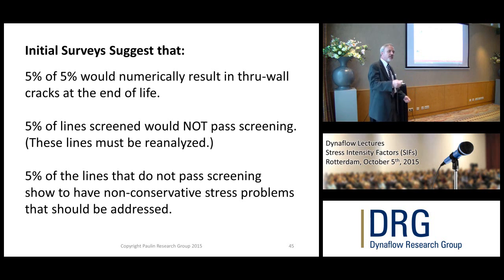And then you have to decide whether you want to start inspecting, and when to start inspecting. Because if you recognize this problem after 10 years and you're not going to have a crack that you can, probability-wise, find until after 20 years, it's a waste of time to inspect. When you do the calculations, you say, Mr. Operating Company Owner, in 10 more years you need to go inspect this point at the next downturn. You take the insulation off, build the scaffolding, and go out, and here is the prescribed inspection procedure you should use.